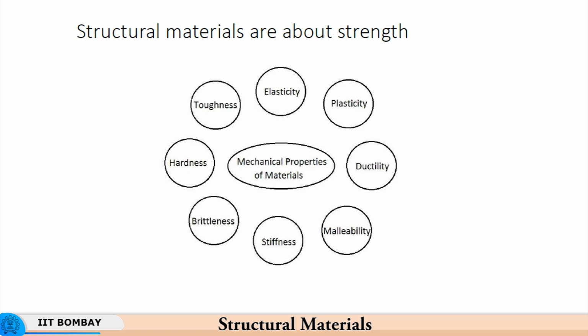to specific shapes and for making lots of pieces of art is done by making a scratch of that particular contour and then just bending it and separating the two pieces along that contour. The glass is easy to break, and therefore, if you make a scratch along a particular line, it is very simple to break it along that line. That is because there is brittleness in the glass.